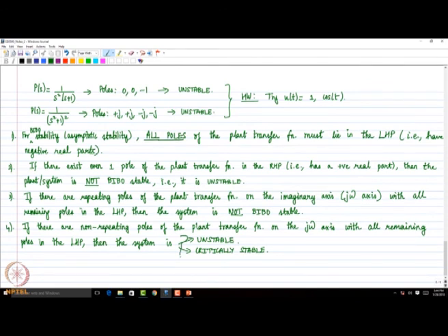Most textbooks will say it's critically or marginally stable, but if we strictly apply the definition of BIBO stability, it's unstable. In stability there cannot be any compromise: either a system is stable or it is not. So if we are strict to that extent, we should call this unstable. But if you say, come on, the output is bounded only for one small group of bounded inputs, well, you call it critically stable or marginally stable.